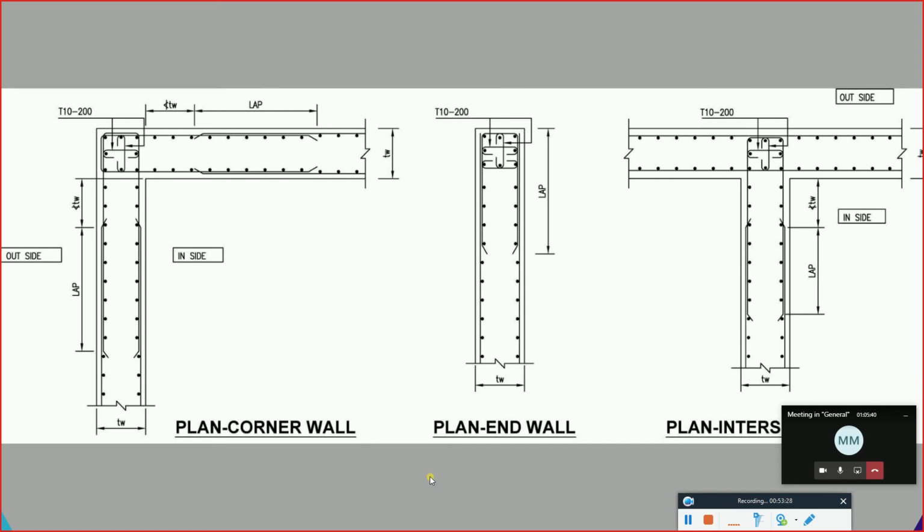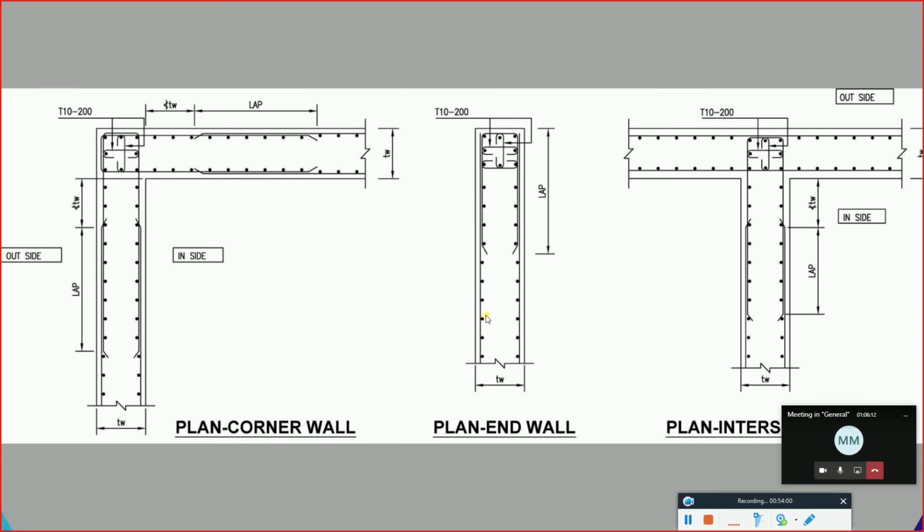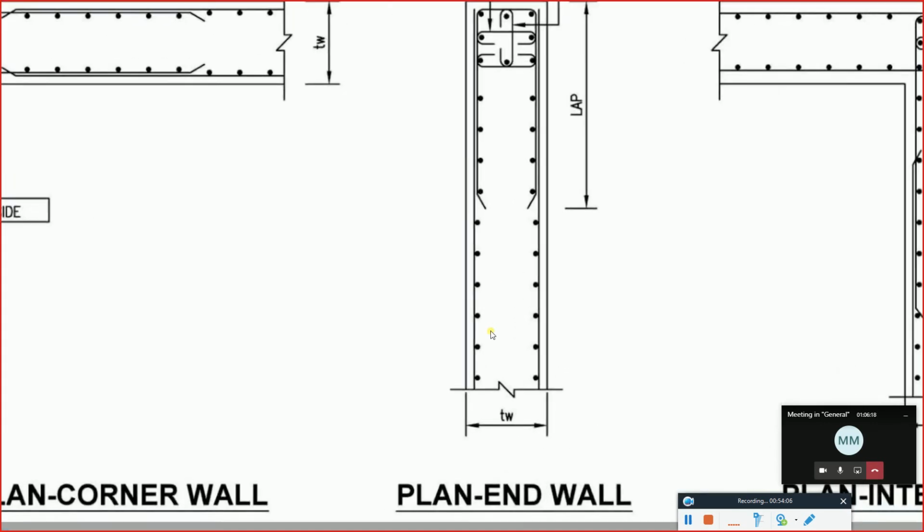Normally for a wall, we have one particular wall. Normally it has a support from this side, and a support from this side, whether it's another wall or a beam. So what goes here, we are having top bending moment, and then bottom bending moment, and then once again top bending moment. How to make that particular reinforcement, we are going to go for a regular wall where we are going to have the reinforcement in this way.